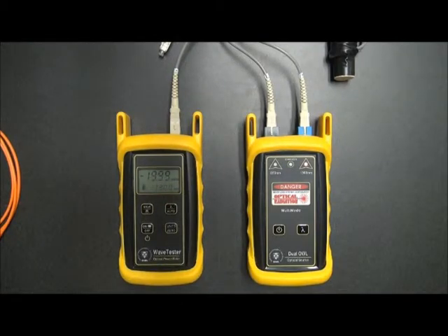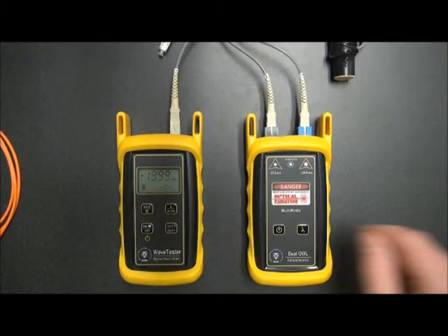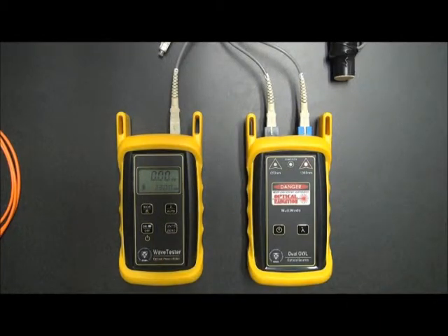Okay, so now you see we have a dBm value of minus 19.99. That's about as close as you can get. What this means is that this patch cable is also good for using for measurement. So we're going to zero out at 1300 as well. Okay, again, 0.00. So what we've done now is we've checked our equipment. We've made sure all the patch cables are good. The equipment is measuring at its calibration level, and we have zeroed out our meter and source together. Now it is time to take readings.